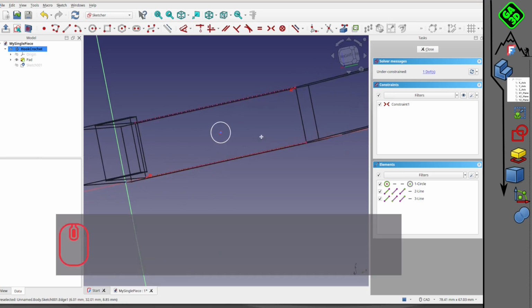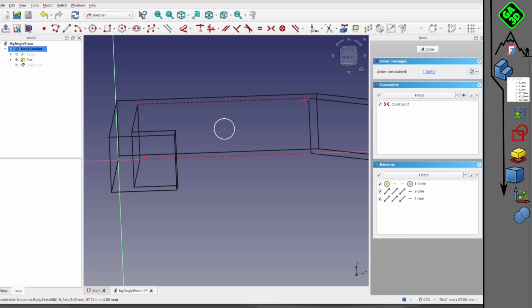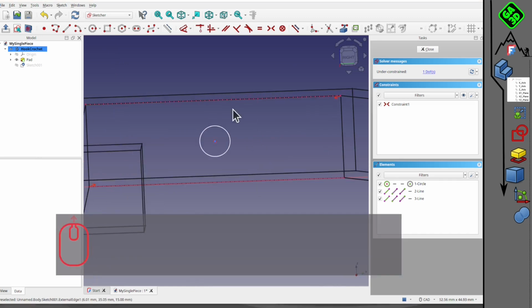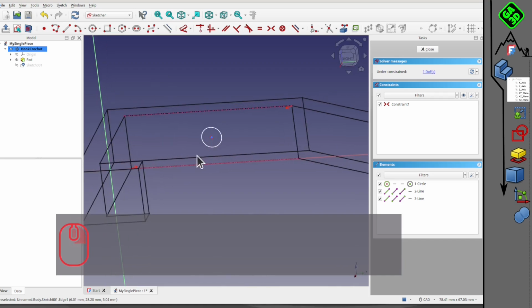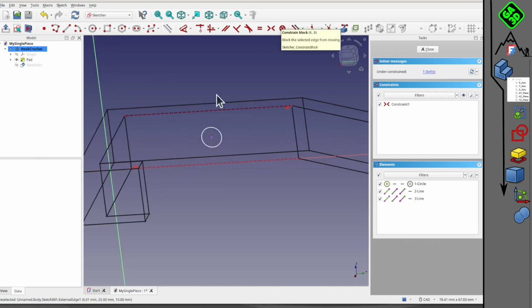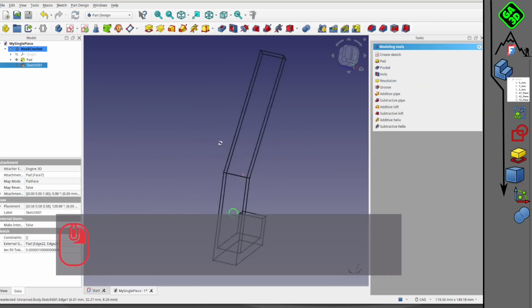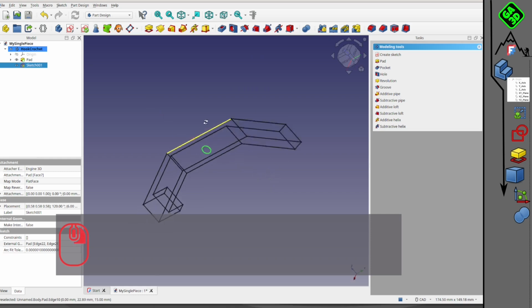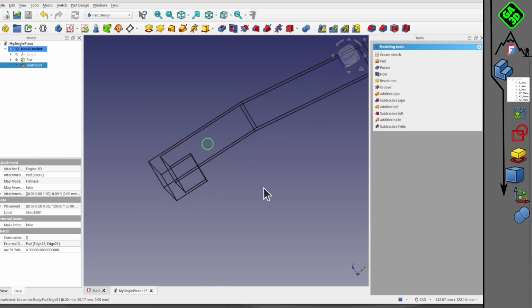You could set the diameter of the circle. But there is a tool that is more practical, because it's tiring to know the diameters of screws, etc. There's the drilling tool. It will create a screw passage wherever there's a circle in your sketch. So the principle is simply to position your circle. It doesn't matter how big the circles are; it's just the position of the circle that creates the screw passage.